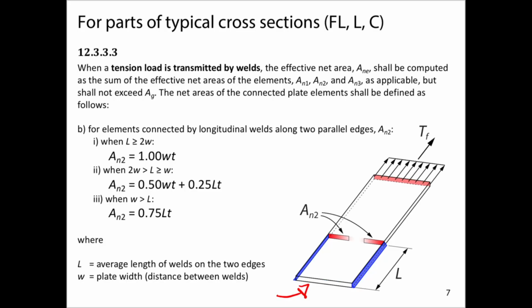It's not always practical to have that transverse weld, and so sometimes for flat bars we might just weld it in an arrangement where we have two longitudinal welds instead. And again, as the engineer, you don't know L, right? You don't know when you're specifying this flat bar how much weld length they're going to specify. The fabricator is probably going to try and keep that relatively small so that their gusset plate doesn't get too big.